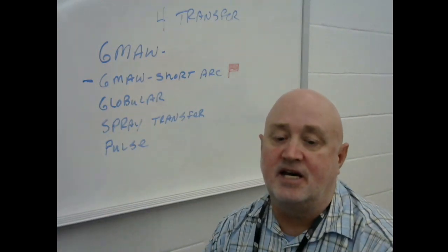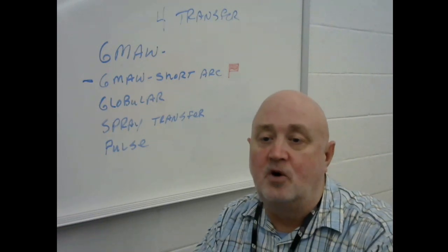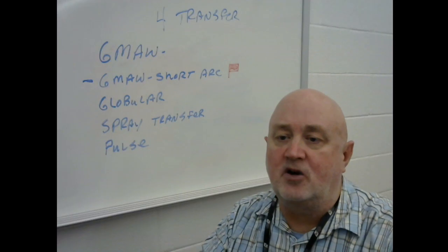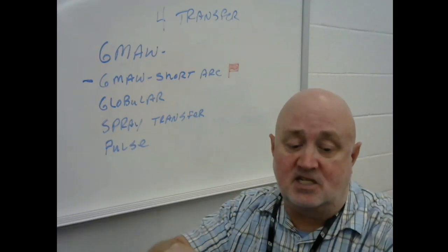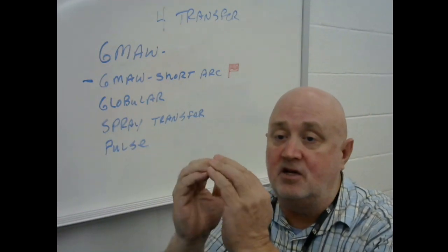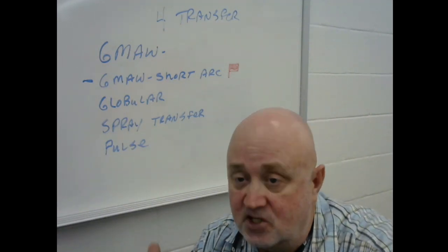I've seen bend tests where the weld looks absolutely wonderful, and then they'll do a bend test on it. You tested a welder. This was earlier on in my career, and it would just snap. It would be like snapping a twig. When it would go through the fixture, it wouldn't bend, and you wouldn't end up with a horseshoe. It would just snap. You'd have two pieces because it didn't tie in.